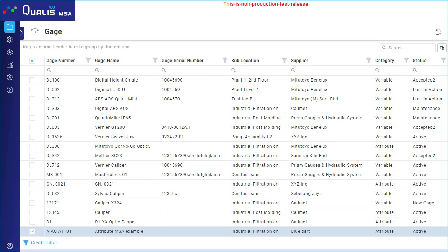method to inspect quality. For example, in FMEA, we must score detection at least with a 6 out of 10 if Attribute MSA studies are done with good results, but more often it is a 7 or 8. So it is important to assess if an attribute inspection is acceptable. In this video, we'll explain how the Attribute MSA study can be done in the Datalyzer Qualis Gage Management software.